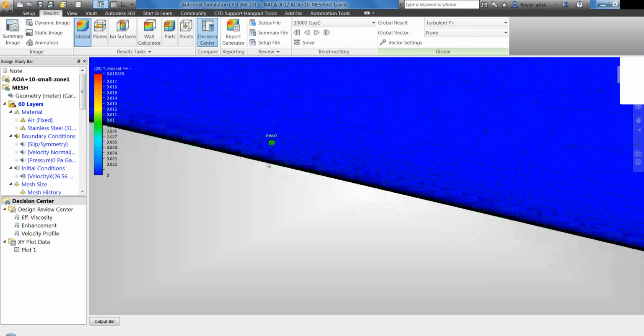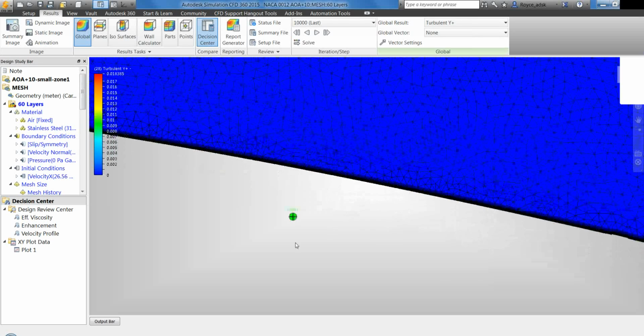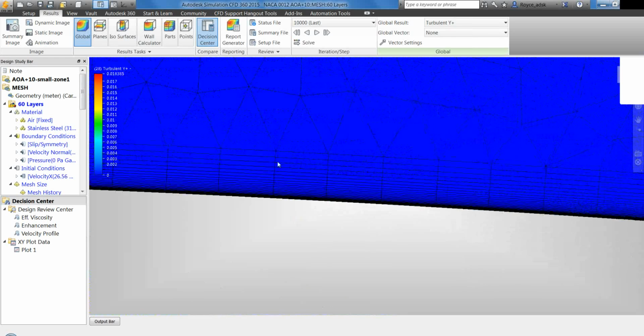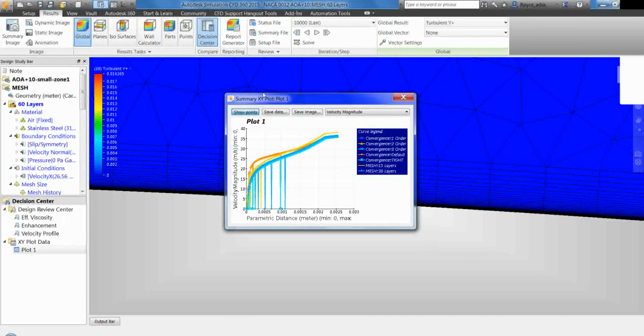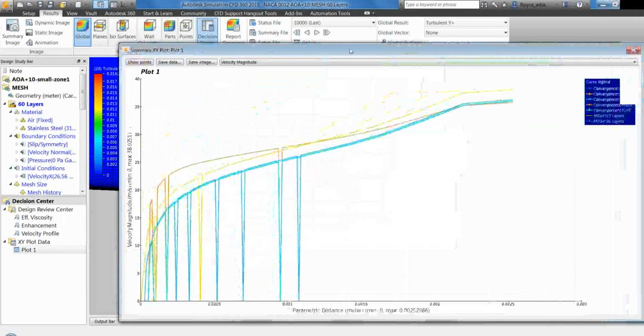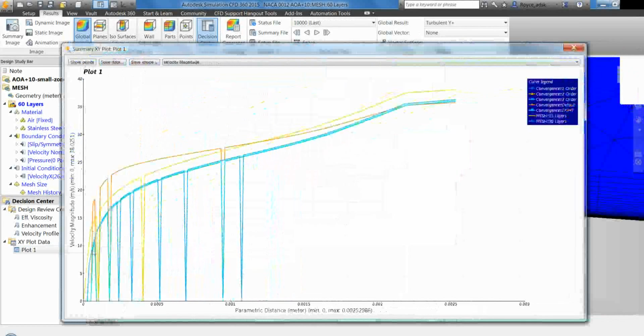The outer constraint, though, is less defined. How do you really assess how thick this layer needs to be? Because it does do a better job to capture that boundary layer. And if you look at an XY plot of multiple runs and look at what that boundary layer looks like, you can see right away, this is our sharp gradient. That's why we need all those mesh element points coming right in the early portion away from the wall. And eventually we start getting to this linear portion of growth, once we get through the initial hump of the